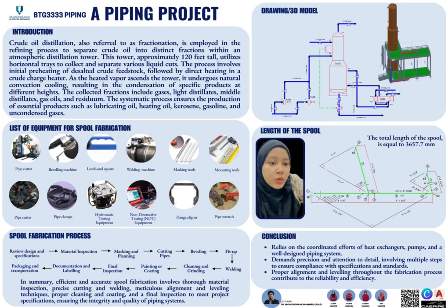For pipe 2, the length of the 90 elbow long radius according to class 40 is equal to 152 mm. It also involves the equal tee according to class 40, which is 105 mm, and we assume the root gap is 8 mm because it has two joints on it. So the total length of pipe 2 is about 1995.5 mm.